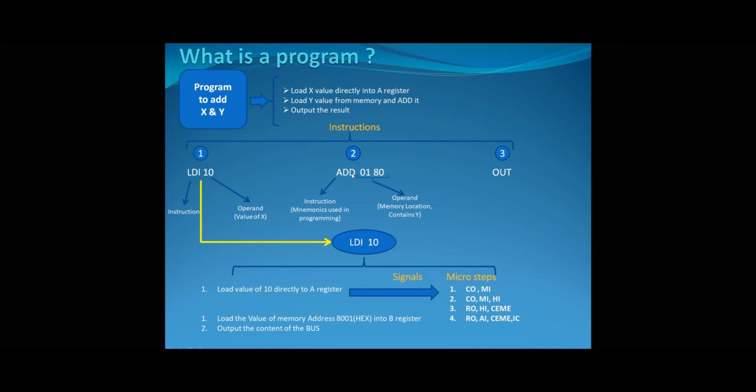That normally means the add instruction in our computer. By the way, we will be building those instructions later in more detail, and even today we're going to talk about some of those. But for now, I'm trying to go step by step and describe this program in plain English and then see how it translates into different instructions. And finally, the last step: because we loaded x into A, and we loaded y probably into the B register, our ALU does the addition of those automatically, and the output will be in our ALU register. Then finally, we could output that to our output display, whatever it is. In our case, it's a UART.